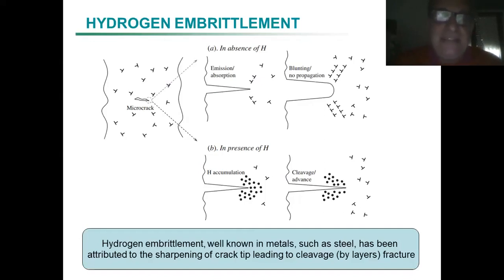If hydrogen is there, there comes a very acid environment, so a kind of pit, which results in also blistering. In the end, you see that after this, at the tip of this crack, you might find that there is another area which is gradually penetrated and opened. So the crack becomes longer, and in the end you end up with cleavage.